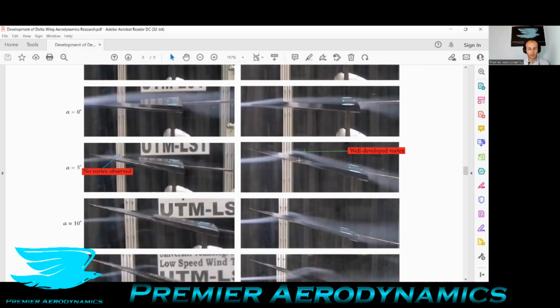And coming back to this other paper, it says that this vortex lift usually varies approximately to the square of the angle of attack. So that means that it's definitely non-linear and it's almost quadratic-like. What's more, it has been observed by Allen and other researchers, as the sweep angle is increased, the strength of the leading edge vortices decreases, while the size of a vortex formed by a roll-up of the vortex sheet is independent of Reynolds number.